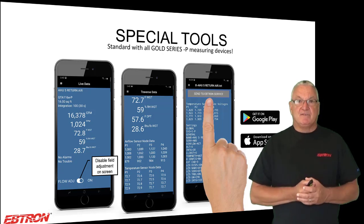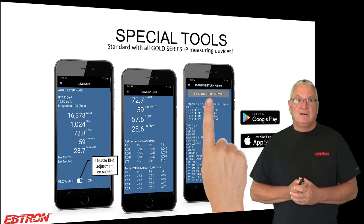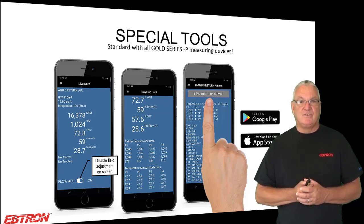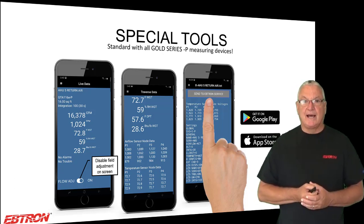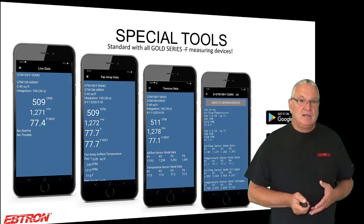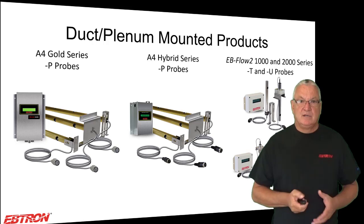I will make a comment right now. This is only available for the Gold Series. When you order the Gold Series, make sure you give it a name. If you give it a name, that'll show up. If you look at that left-hand screen, you see the top thing there that says AHU5 return air. That's because somebody gave it that name, okay? It's supported by Android and Apple iOS, okay? When we get into fan measurement, if it's a fan array, we have an additional screen that will give you the individual fan flow measurements.